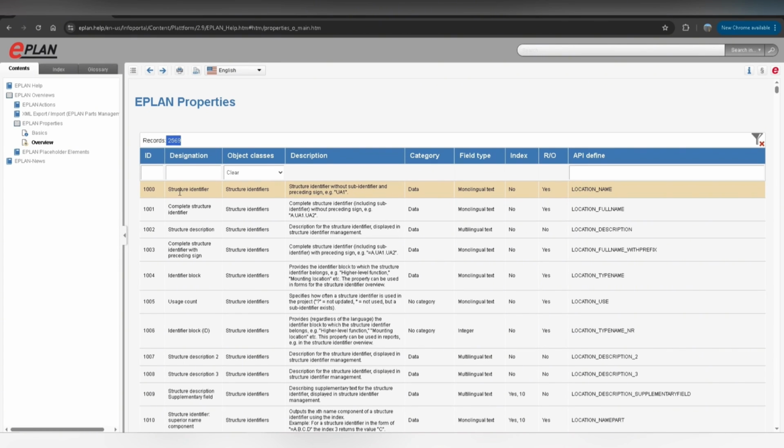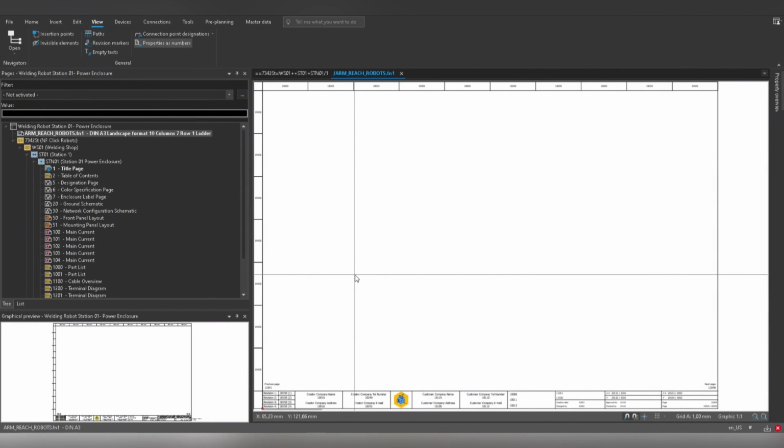If we're using designations, it might be quite difficult for you to collaborate with someone who speaks German or Dutch or another language. So my suggestion is that if you are using EPLAN for just everyday EPLAN editing, designations are important to remember. But if you are scripting or doing EPLAN APIs, it is important for you to remember the EPLAN property IDs. So to conclude this short video and just to answer the student, I'd say focus on understanding how to find the IDs when you need them, but memorizing all of them is unnecessary and inefficient.